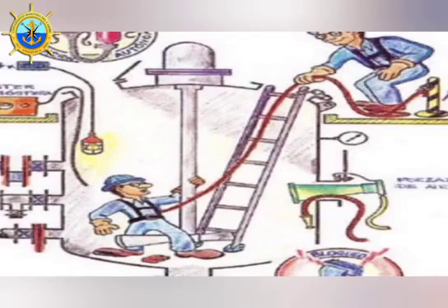Oxygen content, combustible gases, and toxic vapor potential of air pollutants. There shall be no hazardous atmosphere within the space whenever a person enters the interior. The atmosphere of a confined space shall be analyzed using equipment sensitive and specific enough to identify and evaluate any hazardous atmosphere that may exist or arise. You must provide appropriate acceptable entry procedures for the space being entered.